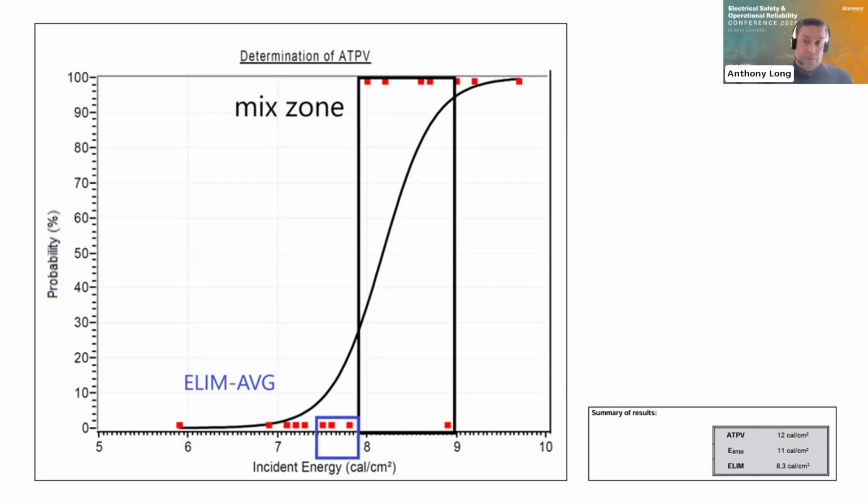On the left-hand side, you've got the probability of an arc flash burn, should I say. At the bottom is 0% probability of a burn, and at the top is 100% probability of a burn. When they are checking what actually happens in the arc flash, it is showing that we've either got a burn or there's no burn. So that's why you've got 0% or 100%.